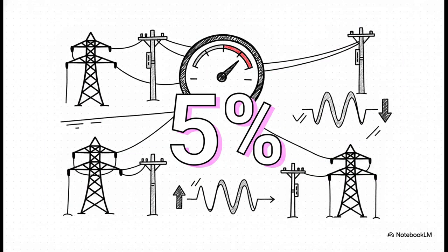Okay, so what is the crucial rule governing all these models? Steady-state voltage regulation. Your absolute North Star as a planning engineer is maintaining that voltage within a strict plus or minus 5% of nominal under peak load. Most electrical codes and utility standards mandate keeping the voltage squarely within a 5 to 10% band, entirely depending on the voltage class. If your models show the voltage sagging below 95% at the receiving end or spiking above 105%, you've got a major engineering problem to solve.